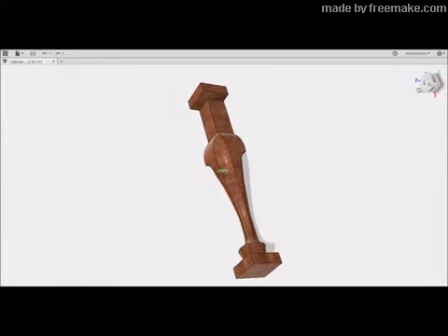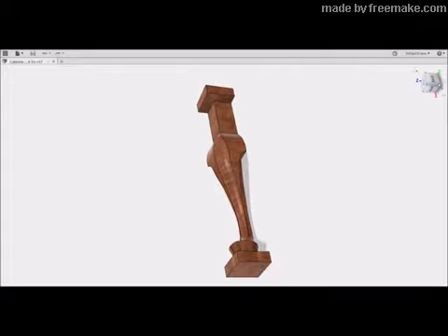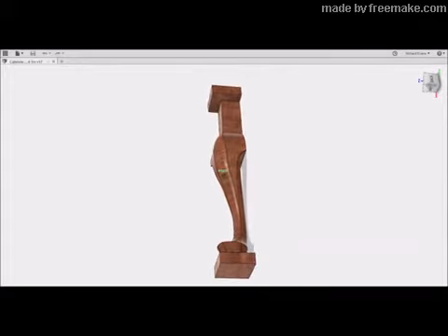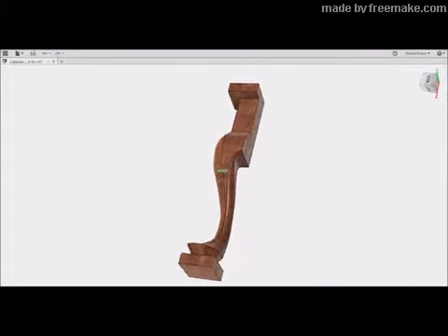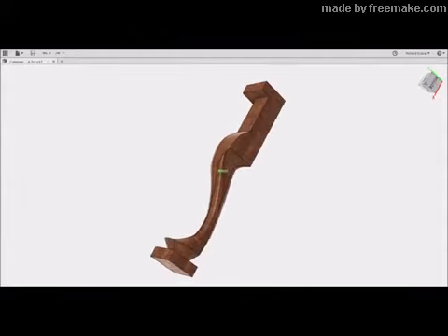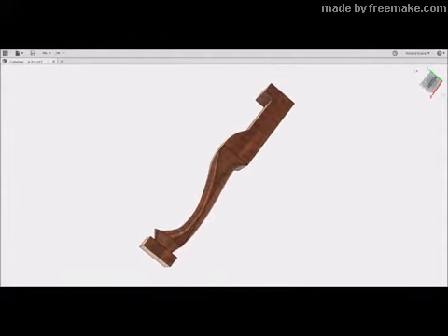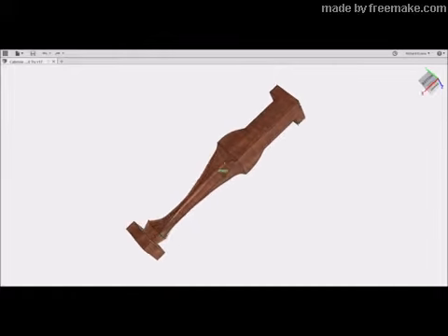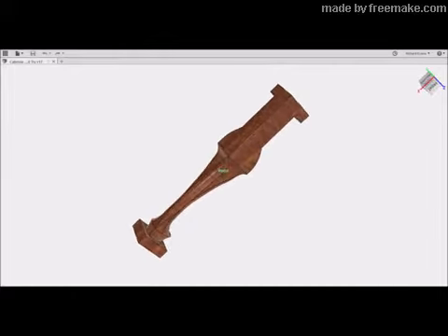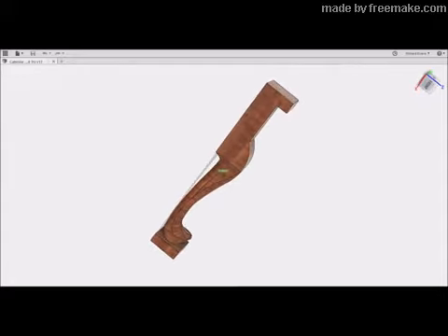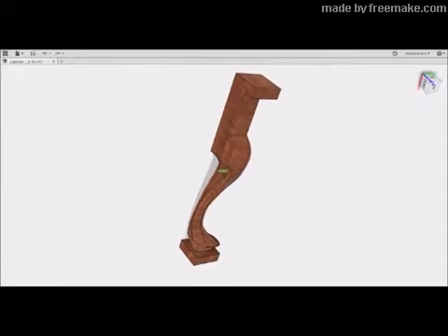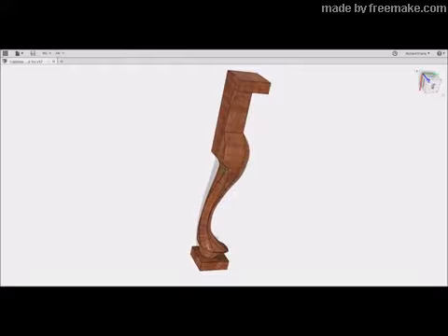Here is the final computer model of the leg. It was surprisingly easy using the CAD software to create this model in Fusion from the template sketch. The blocks at the top and bottom of the leg will be used to register the stock in a holding jig for the CNC machining. These blocks will be cut off after project completion.